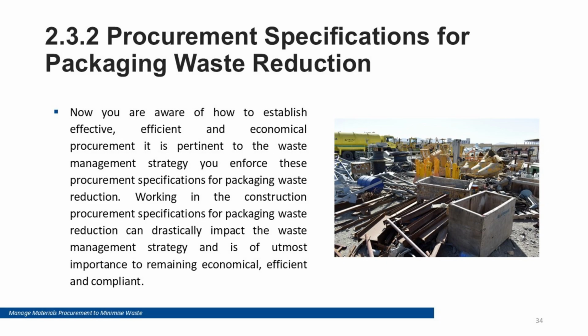Packaging is a common and visible waste stream on construction sites. Procurement specifications can reduce packaging by requiring returnable pallets and reusable containers, reduced plastic wrapping where practical, supplier take-back for packaging and offcuts, and clear labelling to support recycling.